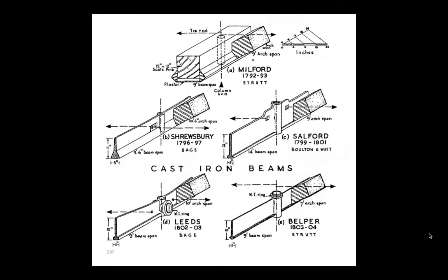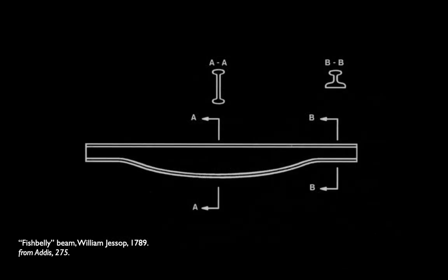These, of course, aren't terribly efficient, right? They don't look very much like today's W shapes. They've just got these teeny tiny flanges. But builders start to realize, and building scientists start to realize, that the larger those flanges are, or to put it more accurately, the more of the section's material that ends up in the flange instead of the web, the more effective and the more efficient these beams get.